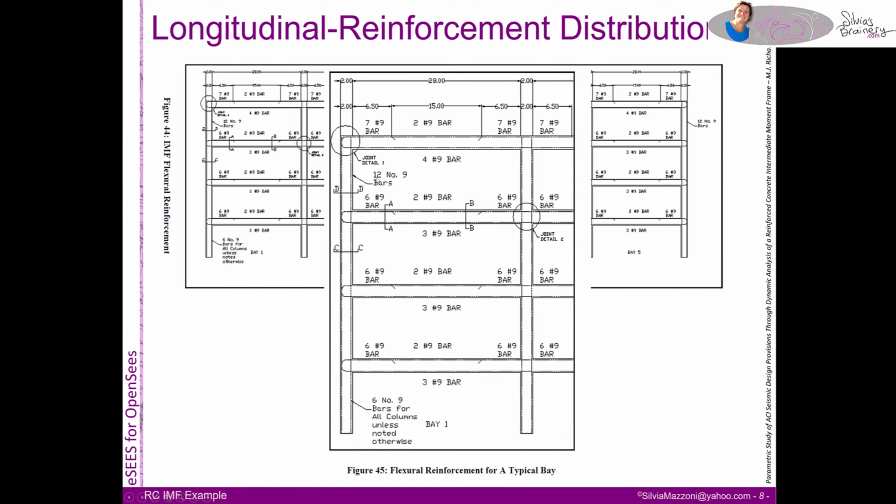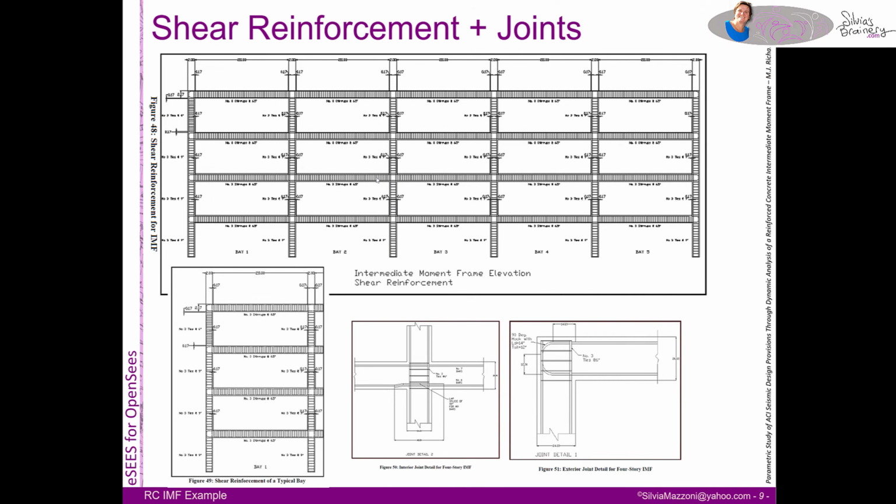So this is what I have, and this is what I went with. They've got information even about the shear and the joint reinforcement. I am not modeling shear deformations nor joint deformations, so that's something to keep in mind.